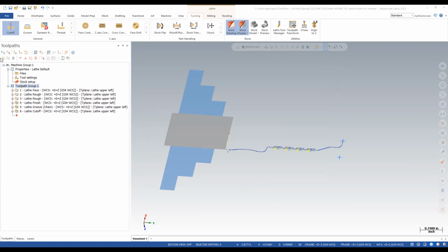It just does it because it's a thing in the post. So all I really need to do is delete the V. I'm just going to have you take the UVW out completely. I won't confuse you then. So we won't have any incremental in it. Sound good? So how many times does that happen? 4 times, because how many tools are there? 4. So that's at the end of every tool change. So I look for the next tool change. Look at that, UVW, just take it out.